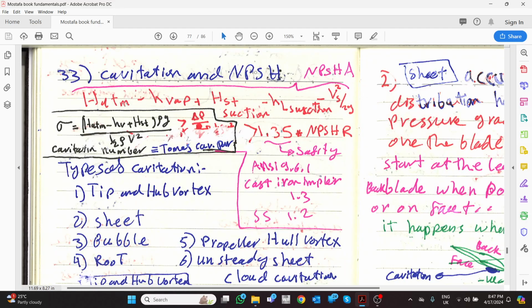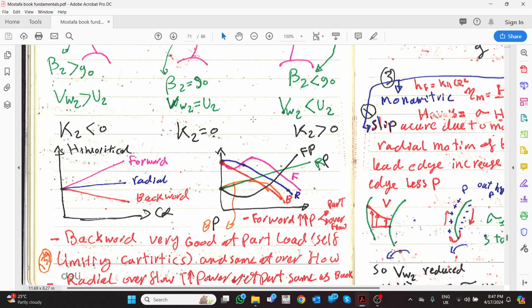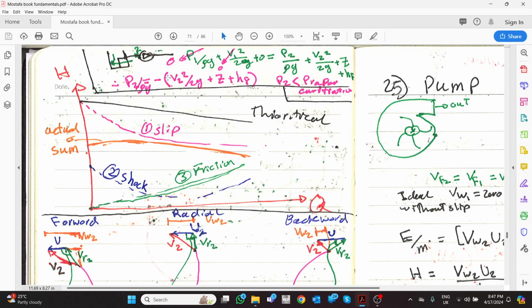So we know that there is net positive suction head. As we discussed, it is the same as what we did before, with atmospheric pressure. Neglect this one for now. So the static head at the suction minus the losses minus the kinetic energy returned back. The static head plus the friction plus the kinetic.